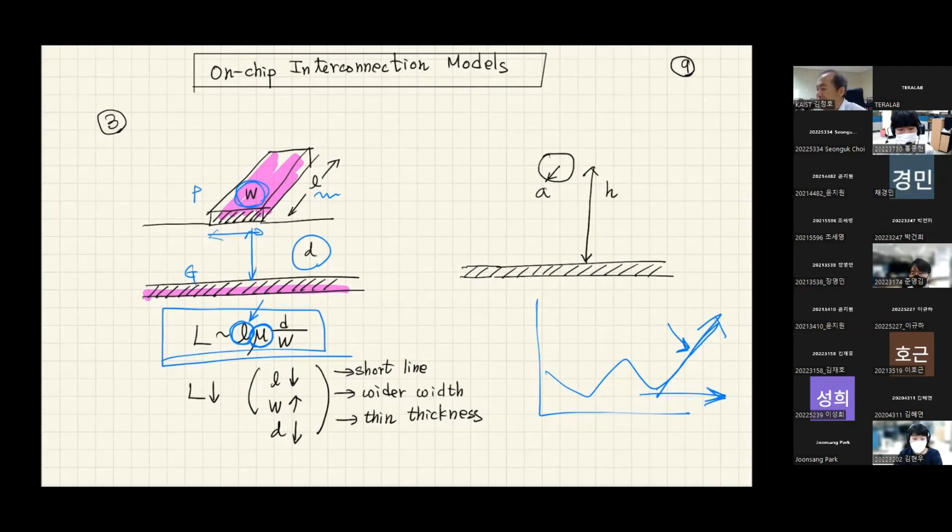In some applications, you may have some magnetic material, but one interesting thing is that in the gigahertz range, I couldn't see any magnetic materials. They are becoming normal material at the gigahertz range. So magnetic permeability is going to be almost the same. The number one parameter is reducing the length of interconnection.